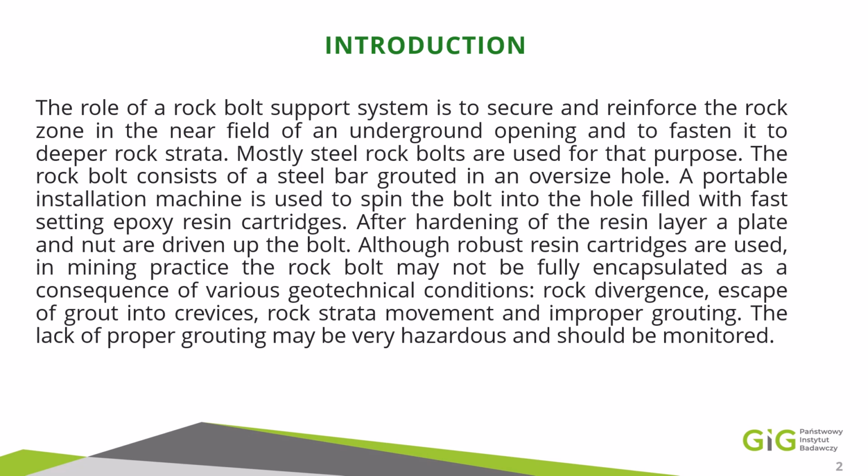The rock bolt may not be fully encapsulated, as a consequence of various geotechnical conditions like rock divergence, escape of grout into crevices, rock strata movement. There may be also technical problems which lead to improper grouting. So the lack of proper grouting is quite hazardous and should be monitored.